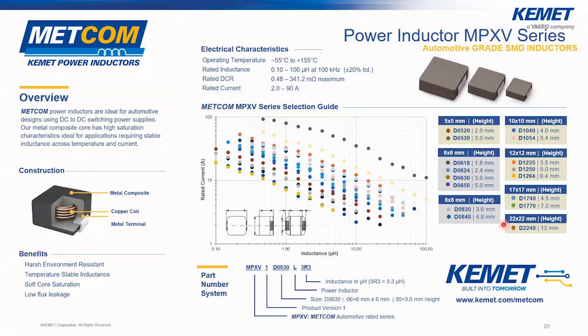But there is a new extension of this series that will be released soon to go down to 4 by 4 and to have more inductance values to cover. An important point to highlight is the temperature, since for electric compressors this is an important parameter. Our MPEV series can handle from minus 55 up to 155 degrees. And that is our SMD parts solution.